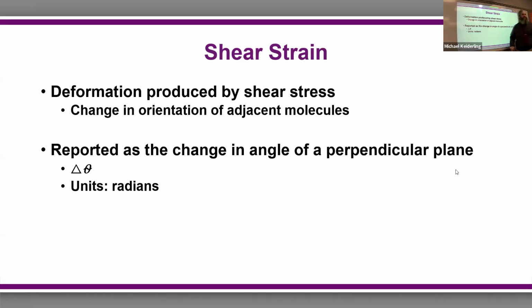It's not really even a formula for that. Just, you know, what happened. The plane started like this, and now because of the shear, it's tilted. How much did it rotate by? It's still a ratio, radians. It's arc length over initial length.